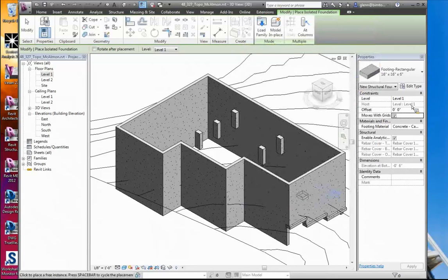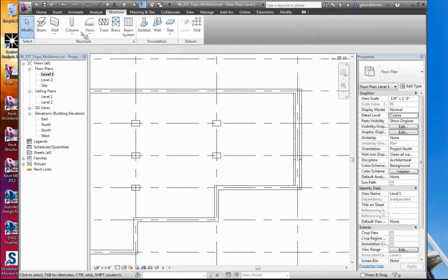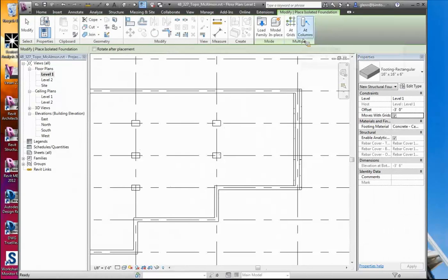Now, in terms of where we're going to put them, we actually put the height. So level 1 minus 3, if that's the height. Then you need to adjust those so the height individually matches where they need to be, if they were following the slope on down. Actually, let me do it in the floor plan view. I think it may be a little bit easier to do in that view, because in the floor plan view, I can do this thing where it says add columns. So I could place them just by getting that grid intersection.